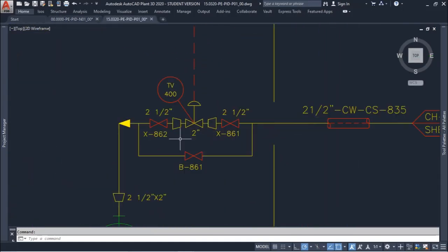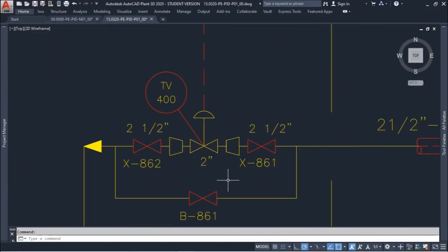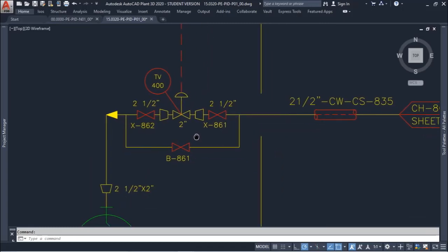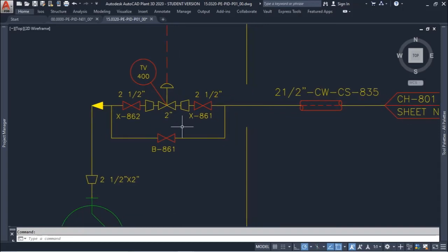In this P&ID, we don't have this kind of information. At first sight, we don't know if the valve safe position is closed or opened. Usually, for a cooling system, it is fail open, because we don't want to take out the refrigeration in a cooling down process.